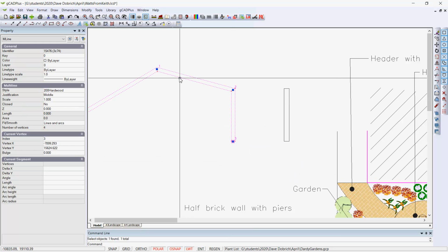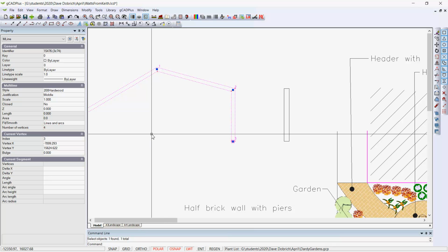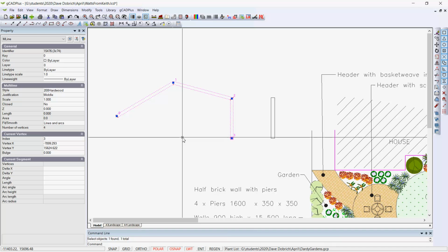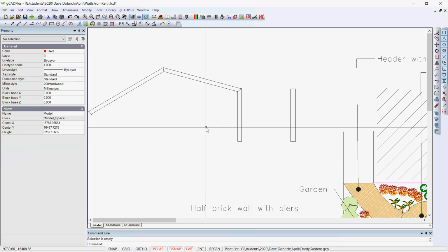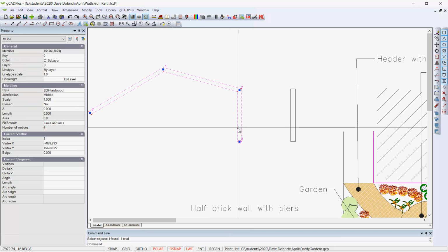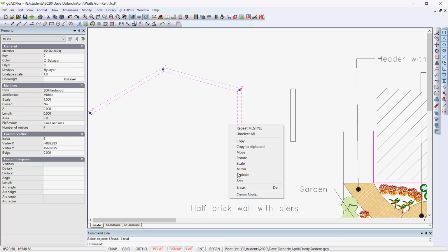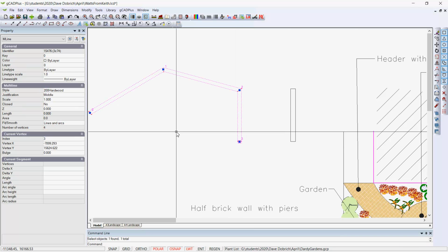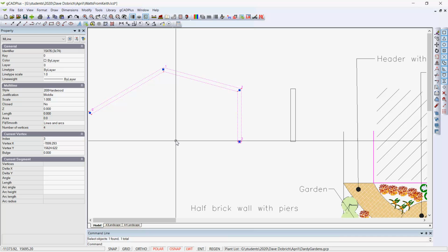When I select the multi-line, it's a complex thing and it's drawn by the settings in that format box, and you can see some grips appear. Unfortunately, multi-lines have some limitations. You can't explode them. If I select this and choose explode, absolutely nothing happens, and perhaps we should include a warning message at that point.